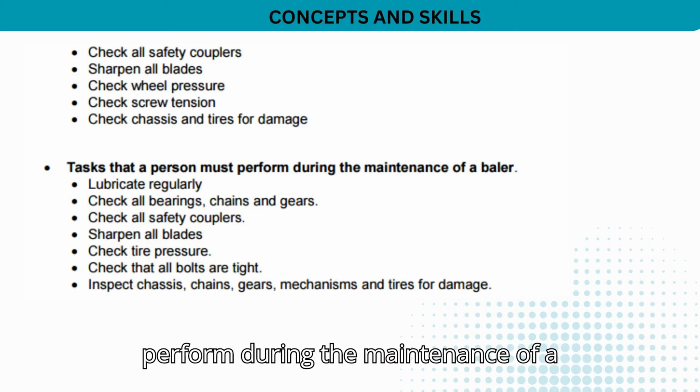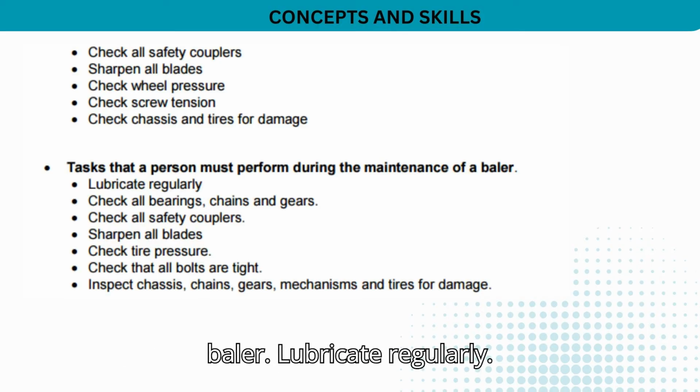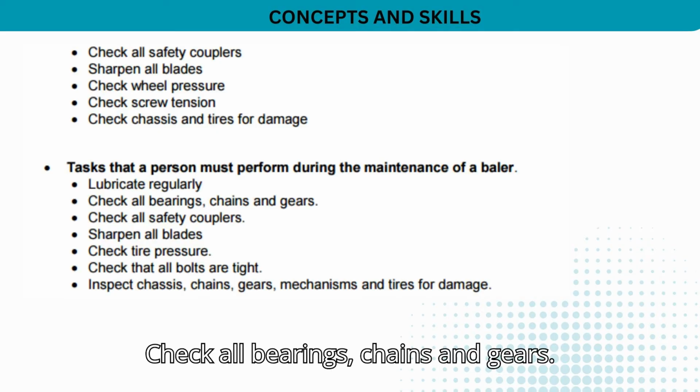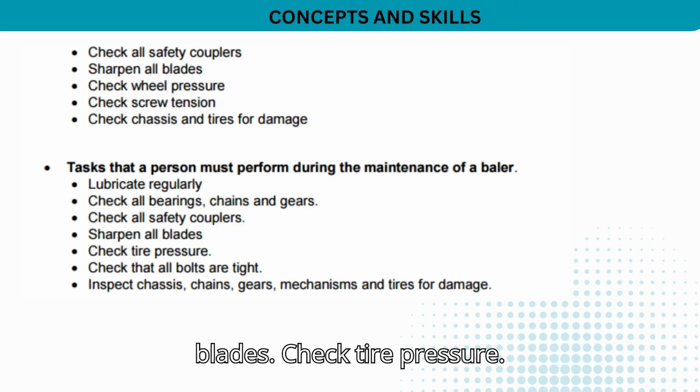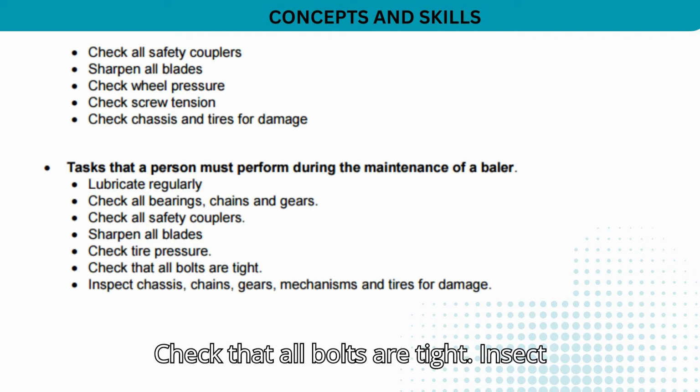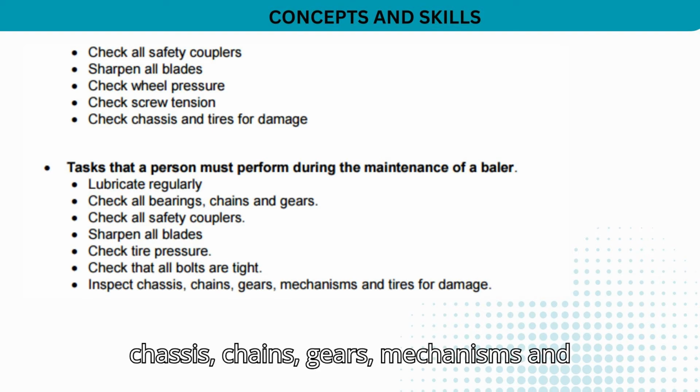Tasks that a person must perform during the maintenance of a baler. Lubricate regularly. Check all bearings, chains and gears. Check all safety couplers. Sharpen all blades. Check tire pressure. Check that all bolts are tight. Inspect chassis, chains, gears, mechanisms and tires for damage.